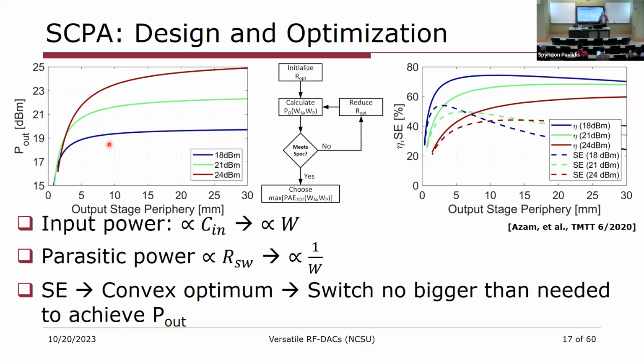Now, beyond that, we might need to subdivide it into multiple slices, and that depends upon how linear our amplifier needs to be, and what level of quantization noise is acceptable in our device, and what the matching capability of our individual process is capable of. And we detail this in some of our journal papers, for instance, in the MTT paper shown here.